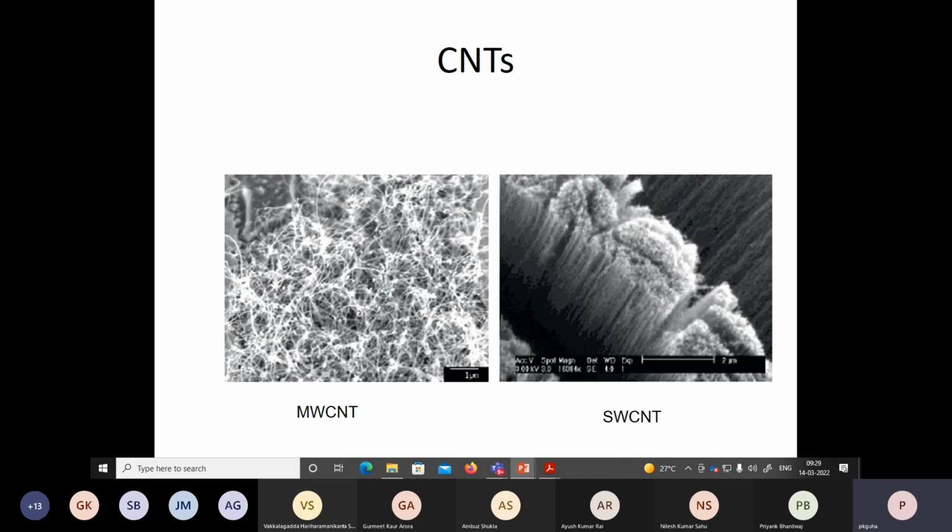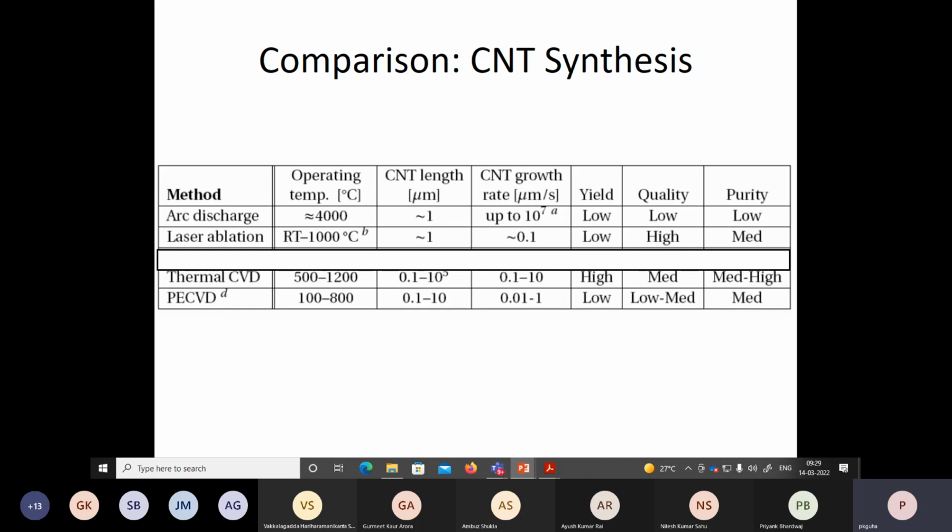So that is why it is kind of difficult to compete with silicon based FET. Whenever you grow carbon nanotube, you will grow it in bunches. Nowadays there are ways to form single carbon nanotube, but still it is nowhere near silicon based FET, where you can accurately make a FET in a specific area of a very large wafer. Here it is not exactly the case, right? So let me just summarize whatever we have mentioned.